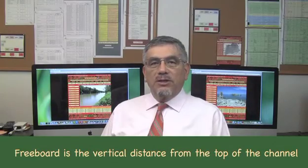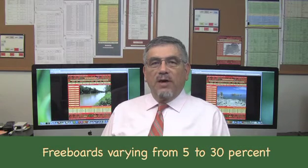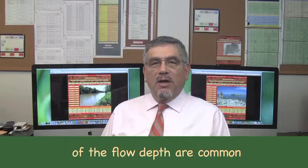Freeboard is the vertical distance from the top of the channel to the design water surface elevation. The freeboard is designed to prevent waves from overtopping the channel. Freeboards varying from 5 to 30% of the flow depth are common. In addition, an adequate freeboard provides protection against eventual flows greater than the design condition. Typical U.S. Bureau of Reclamation practice is 1 foot for small canals to 4 feet for large canals.